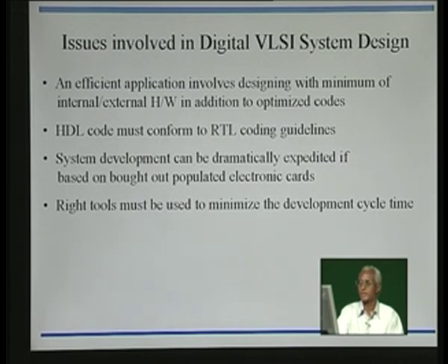The next point is that system development can be dramatically expedited if based on bought out populated electronic cards. In fact, we have used the digital IO card as well as the FPGA card, which are populated and tested, so that you are relieved of the burden of developing this hardware, and that is the positive side. The negative side is that it may not suit your application.